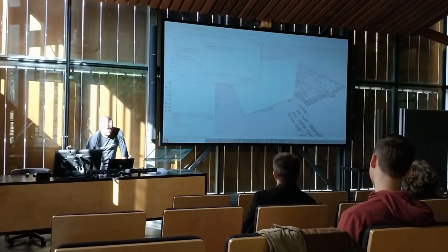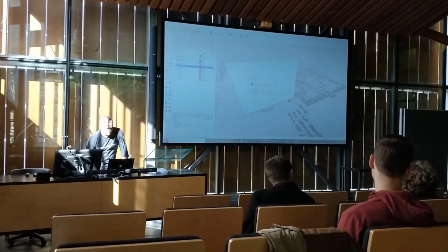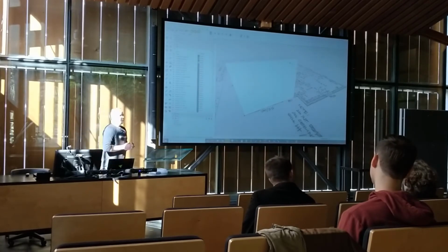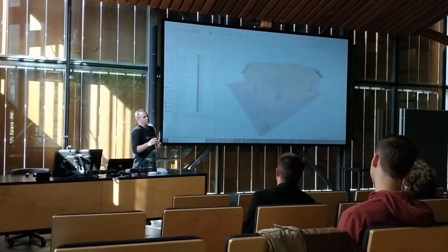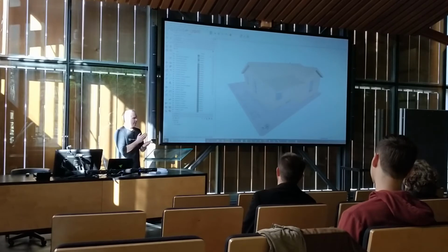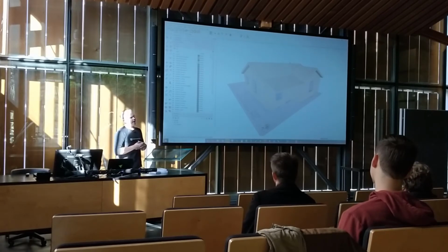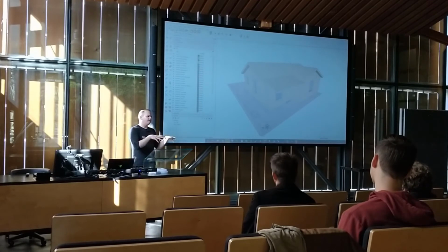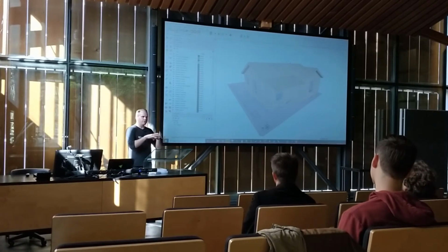When you draw something new, you draw it on layer 0 and then move it to the proper layer. Layer 0 is always your active current layer. To keep it easy for you, just never change the active current layer from layer 0. You can just draw something, and then I'll look at it, and before I get too far, I'll group this thing and go put it where it needs to be.